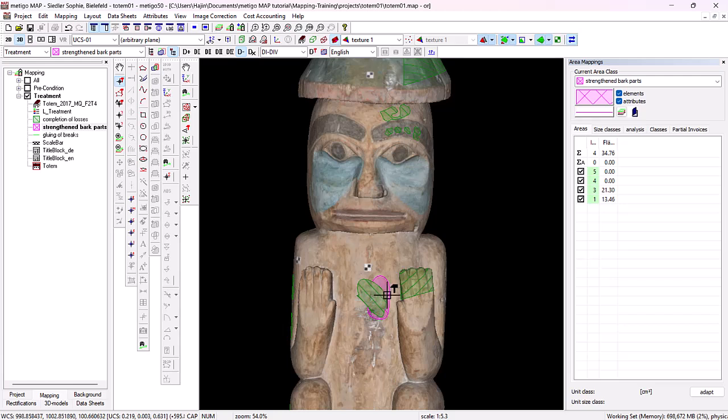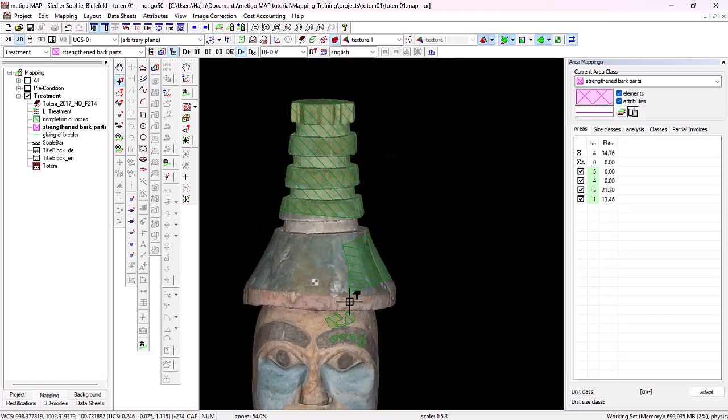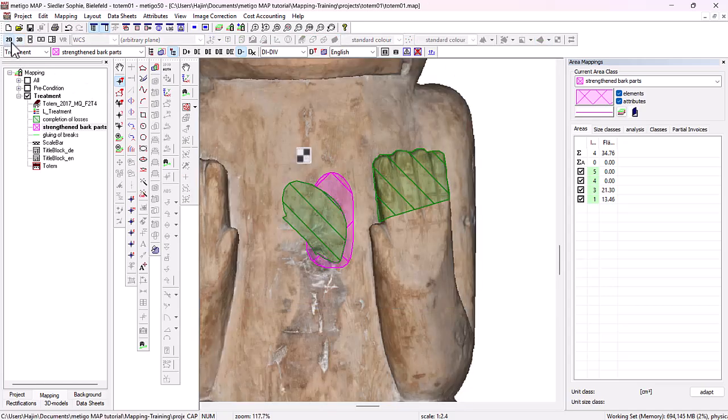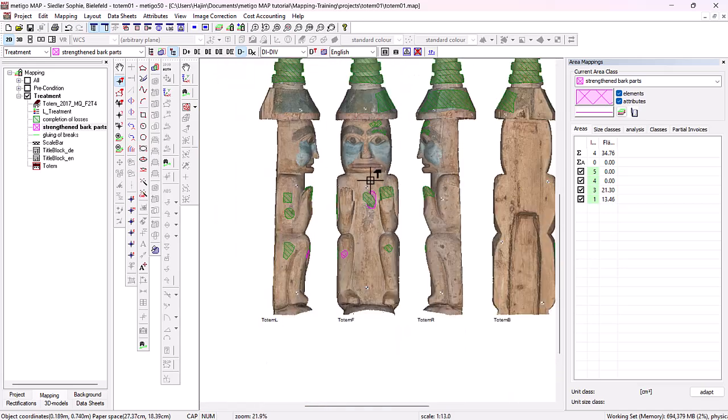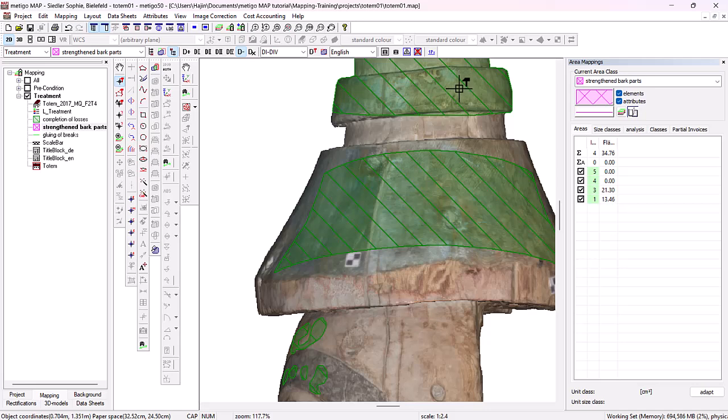In itself, it doesn't really matter which display option you choose, because if you switch to the 2D display, then the hatchings as we know it from 2D mapping are simply chosen orthogonally to the display plane. That is, if I choose a line with 60 degrees to the left, it will be displayed as this regardless of the option as set in the 3D mapping.